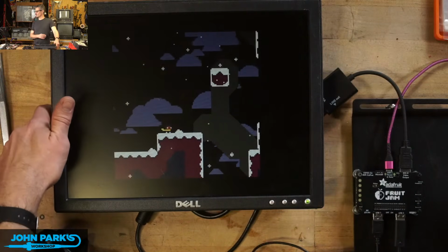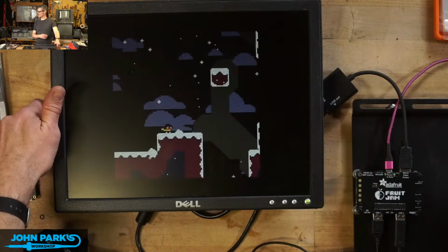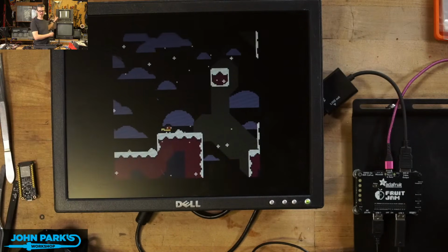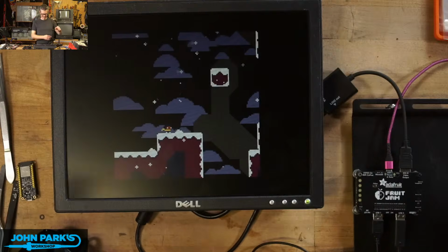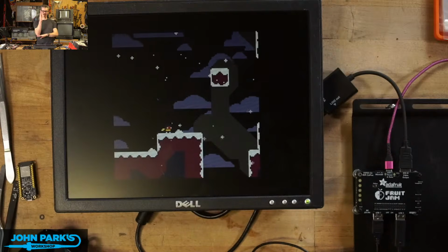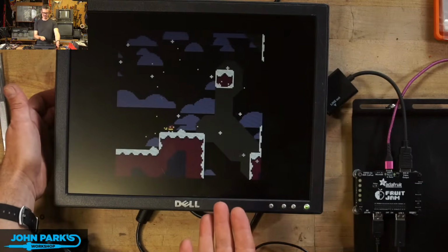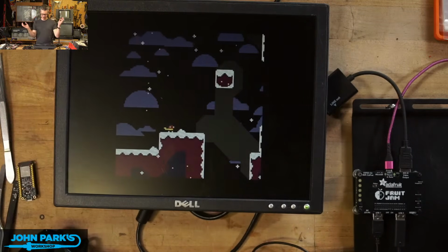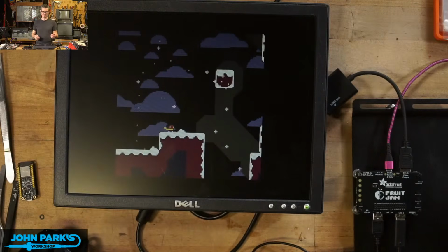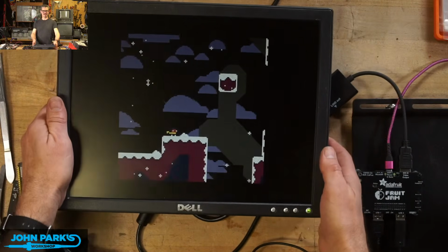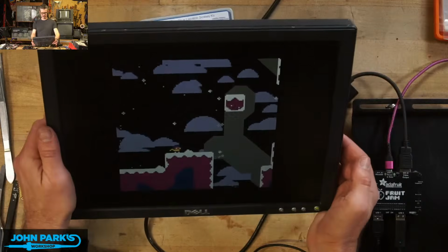Todd said, are there super inadvisable 3D printable VESA mount stands for monitors? Yeah, I had nine of them. I built myself. That's what my wall was on. My advice is just print it vertically, and it's plenty strong, especially for a little monitor like this. If you print it in bed orientation, it just wants to break immediately. The layers just want to delaminate. But yeah, not bad for a cute little monitor.